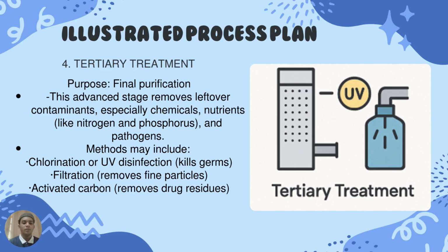Okay, finally, tertiary treatment. Its purpose is final purification. This advanced stage removes leftover contaminants, especially chemicals, nutrients, and pathogens. Methods may include chlorination or UV disinfection, filtration to remove fine particles, and activated carbon to remove drug residues.